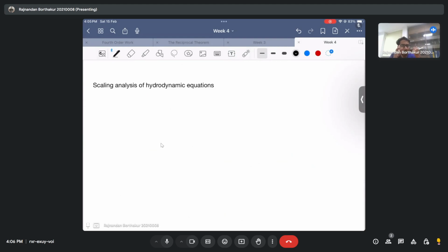Of course it depends on density. If you change the density, the Reynolds number changes, but it is a non-dimensional parameter which helps us give the range. For instance, in pipe flows, if my Reynolds number is greater than, let's say, 2300, the flow is turbulent. That is universal. I hope you realize that for any fluid flowing through a pipe, if my Reynolds number is greater than 2300, I have a transition taking place, or a turbulent flow coming into the picture.